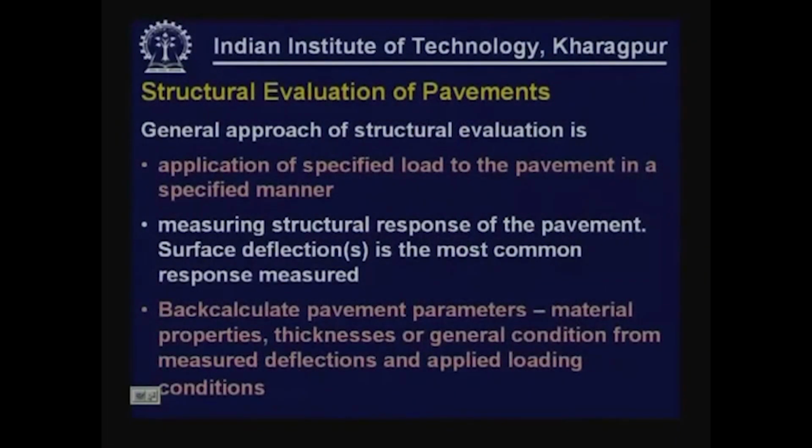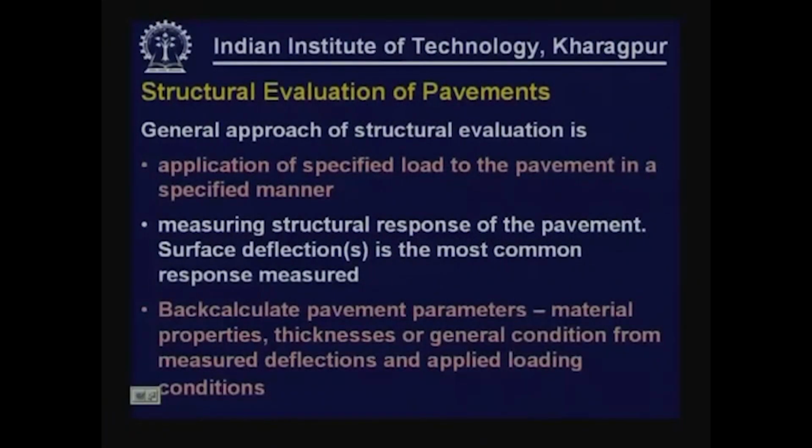The general approach of a structural evaluation method will be to apply a specified load to the pavement in a specified manner. The load applied and the manner in which it is applied has to correspond to the theoretical model that we are using in making interpretations about the pavement condition. Measure structural response of the pavement. After you apply the load, measure the response of the pavement.